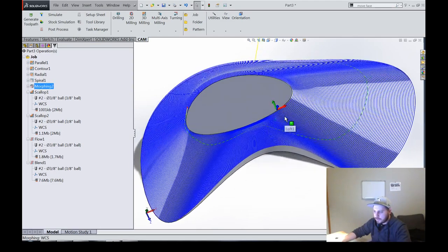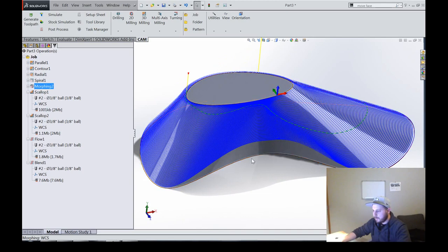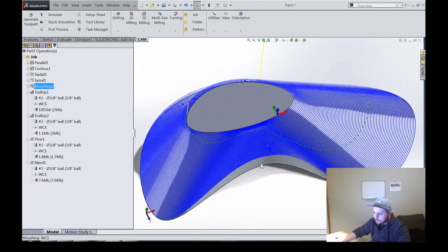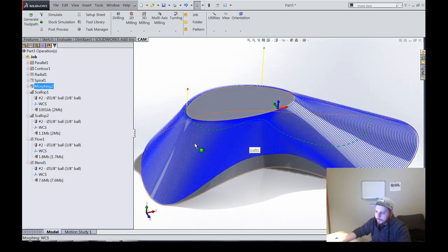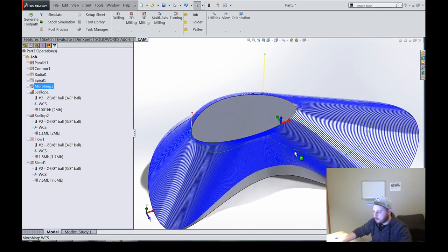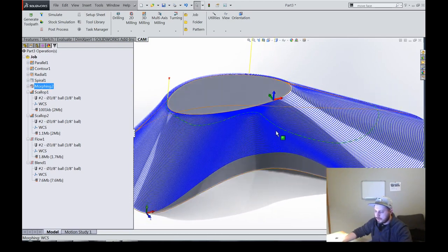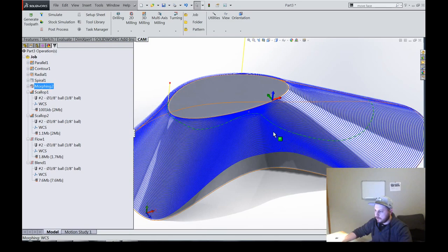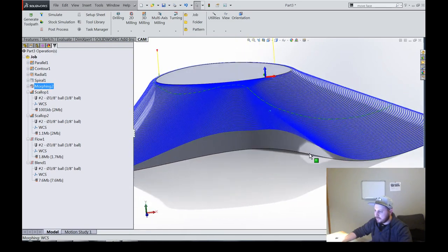In this case, okay, so this is a morphing toolpath. I didn't spend enough time. I should have generated an offset curve to drive this from. I'm not going to bother to though. Morphing definitely does a good job of nailing the attractive, follows geometry, and the smooth. In general, especially on something that's a flowy, curvy thing like this, it's not going to break down too much on real fillets or real geometry like that. It has a tendency to break down.